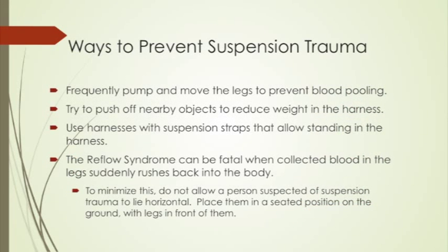There are several ways to prevent suspension trauma. Options include frequently pumping and moving the legs to prevent blood pooling. While suspended, try to push off nearby objects to reduce weight in the harness. Some harnesses with suspension straps allow standing in the harness.